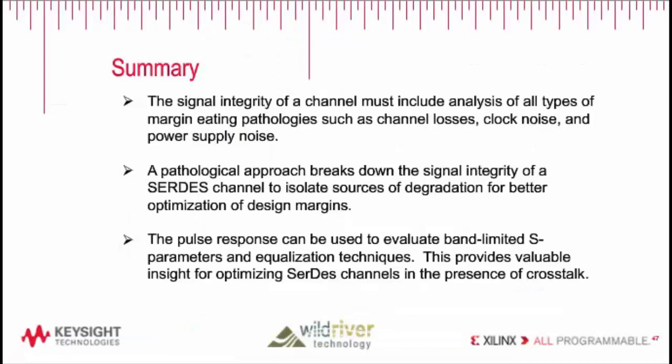So in summary here, Jack did an excellent job of talking about the signal integrity of a channel and how it must include the analysis of all types of margin-eating pathologies, not just channel losses, but also clock noise and power supply noise. And then Al introduced the pathological term to give us some insights into how to break apart the signal integrity, and this approach breaks down the signal integrity of a SerDes channel to isolate sources of degradation for better optimization of design margins. And then finally, I've introduced the pulse response as a new way to evaluate band limit S parameters and equalization techniques, as well as to provide valuable insight for optimizing SerDes channels in the presence of crosstalk.